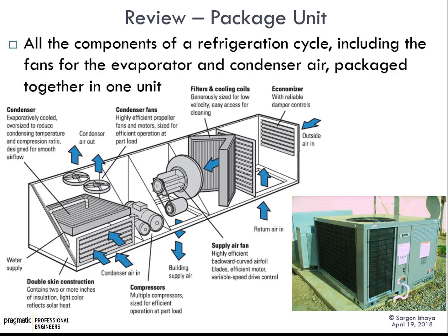And as an engineer, it's very important that when you select package units, fans, valves, or whatever it is for your application, that you confirm that the piece of equipment will fit and function in your system. That's especially true with package units and equipment that has started to encompass more and more features. You have to understand what those features are. You have to understand the capability of the unit that you are selecting, and you have to understand your building well enough to make sure that they fit together. We're going to do that today.